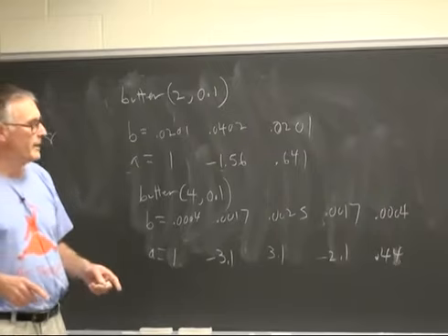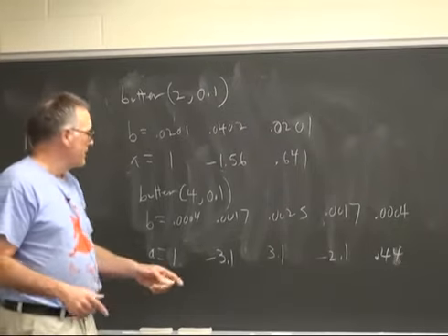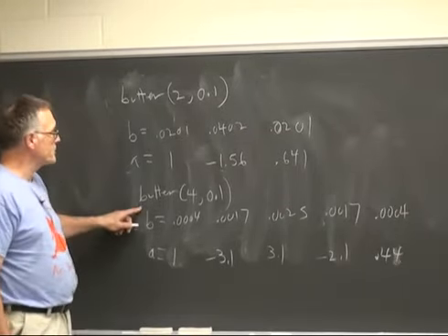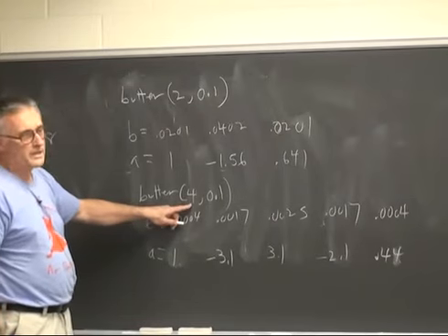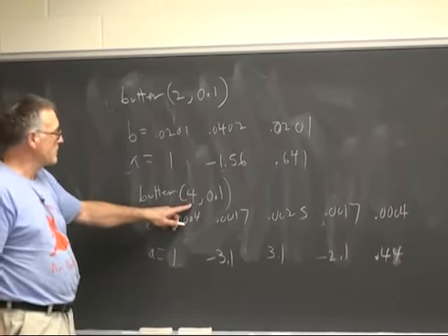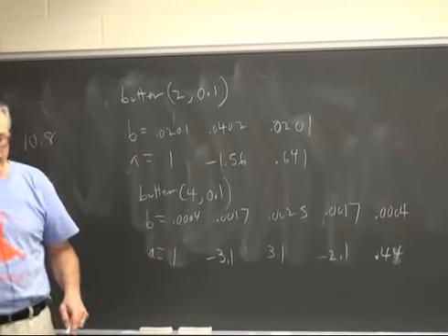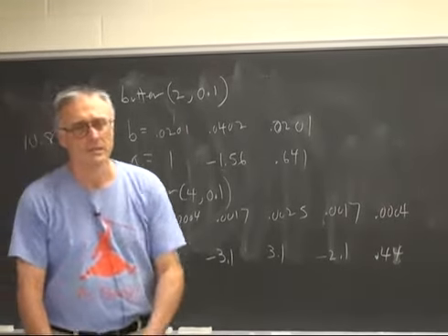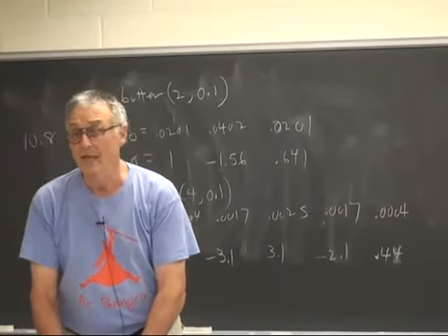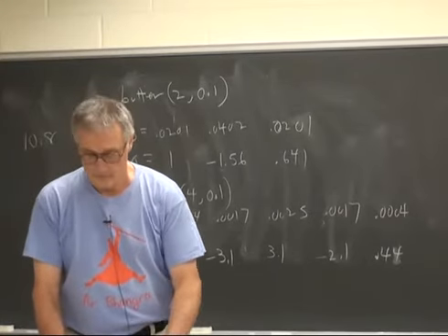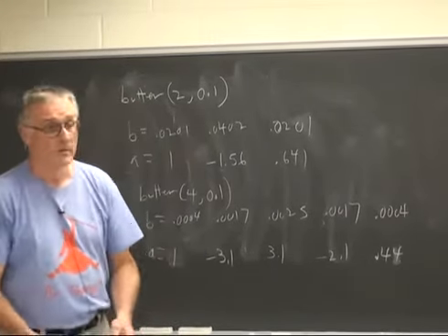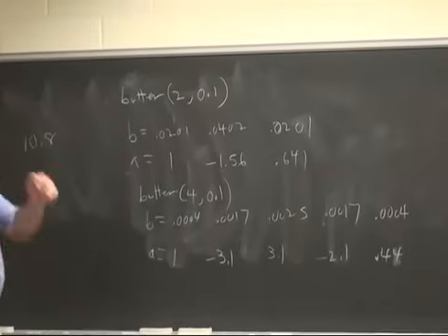Is there a way that we can take these high order filters, 4 or 6 or 8, and factor them in such a way as to minimize the dynamic range of the filter coefficients? And it turns out there is.